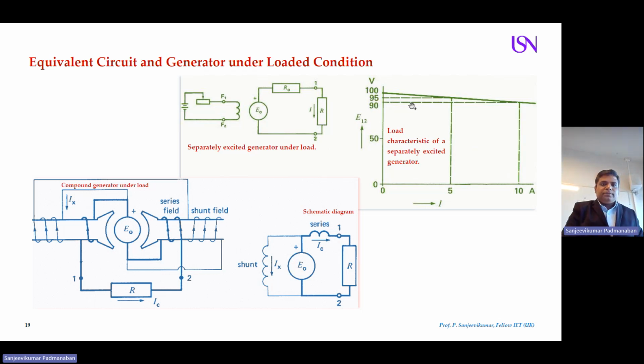What is a compound motor? Look at the diagram. So you have a field winding, and the field winding has the coil. Then you have an armature winding, and this armature winding is connected additionally with a series winding. You can have a look. There is a series winding. There is a shunt winding. So a series connection and an additional shunt connection included within the circuit is called a compound motor.